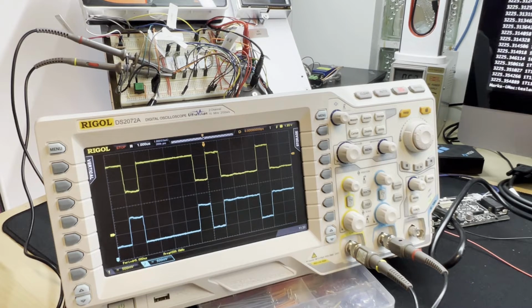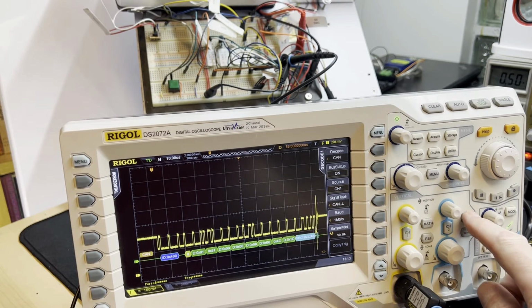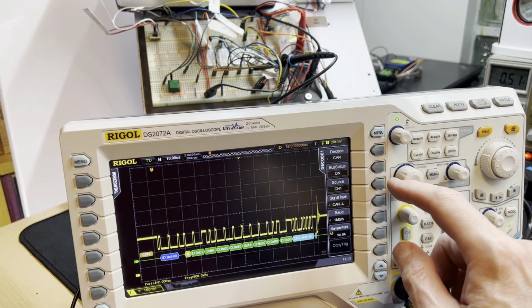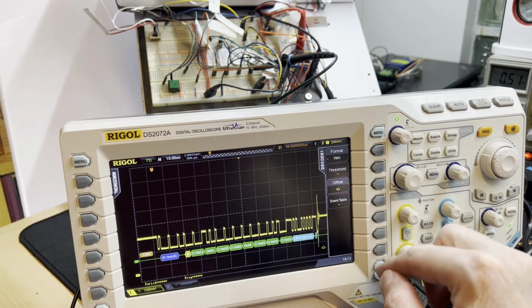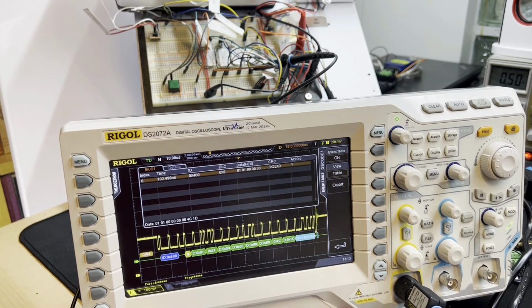With this digital oscilloscope, we can go further and configure it to actually decode the CAN bus data from the electrical signals seen. For this, we only need to look at one signal line, and we've chosen and configured for CAN low. Let's turn on the decode so that we can see the data as annotation under the waveform. We can also turn on a table to show us the messages seen on the bus in a more human-readable format.